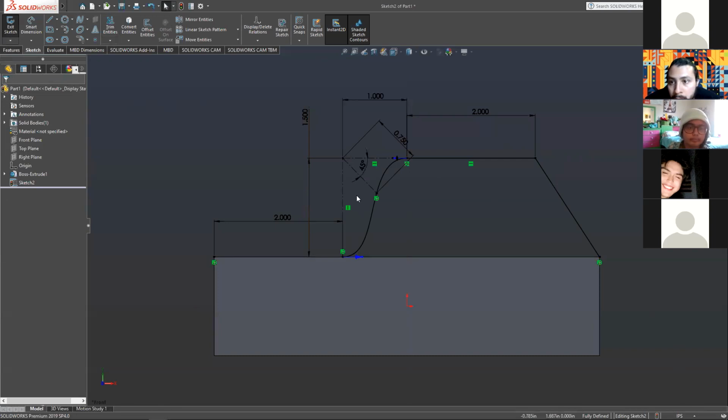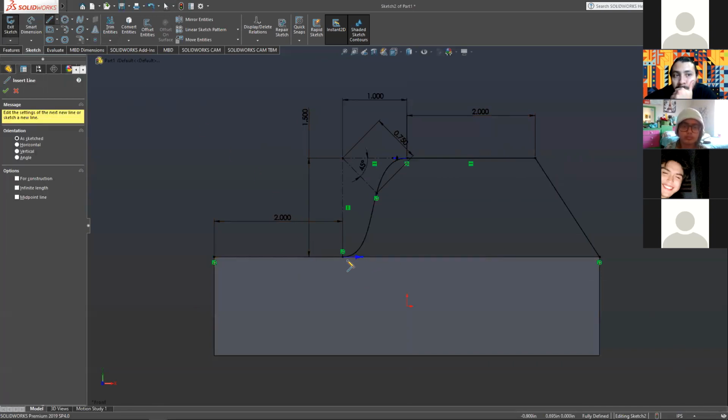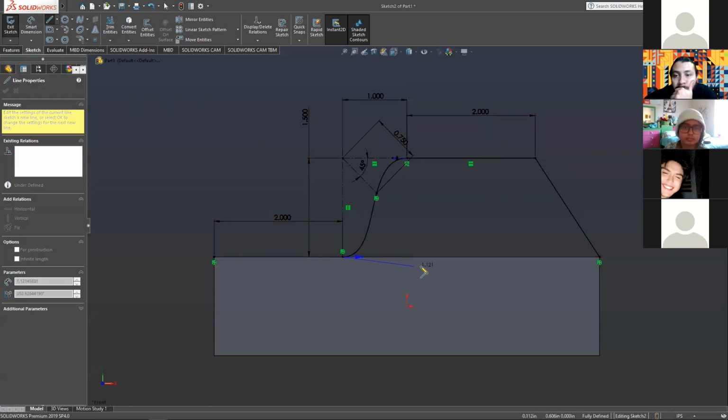All right. Now, in order to project a drawing in SolidWorks, it has to be a closed shape. You can't have open shapes. So this right now, even though it looks like it's complete, because it's on this edge, it's not. It's an open shape because we only have this line and this angled line. So we need to select line and complete the shape, selecting from this point to this end. And bam, see, it even shades it in when it's complete.